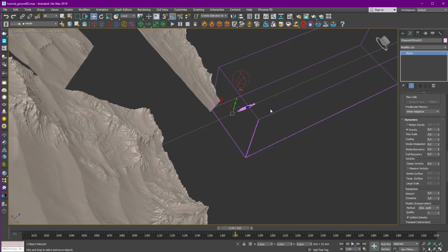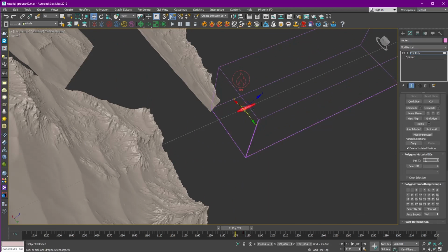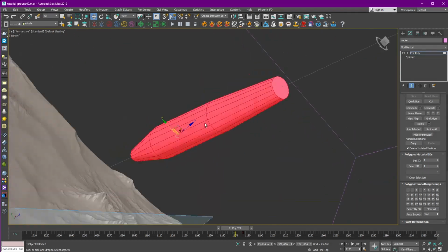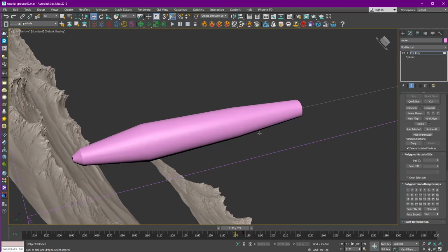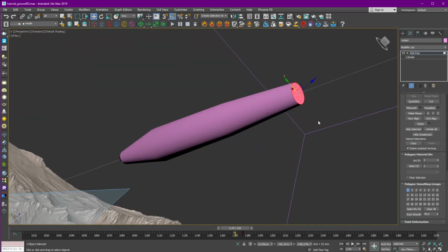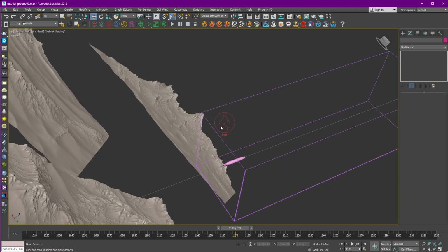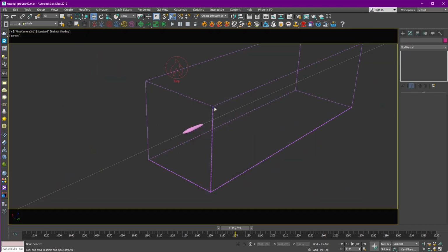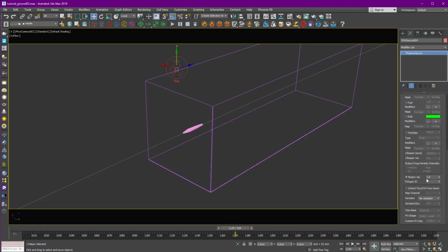And one important trick for the rocket body: we need to set all polygons to channel 1, ID 1, and the backside ID 2. Later in our source object, we will add the whole rocket body, set some outgoing velocity, temperature, and so on.